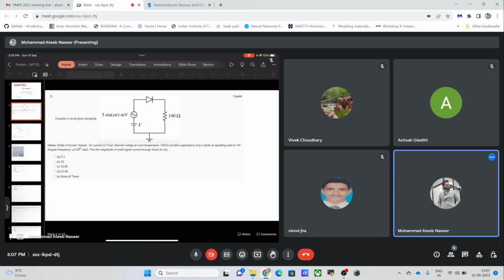For example, we can have a band where the P material has a much larger band gap and the N material has a smaller band gap, lying between the conduction and valence band of the P material, as a result of which we have a type 1 heterostructure. So there are different types of heterostructures when we deal with these junctions.